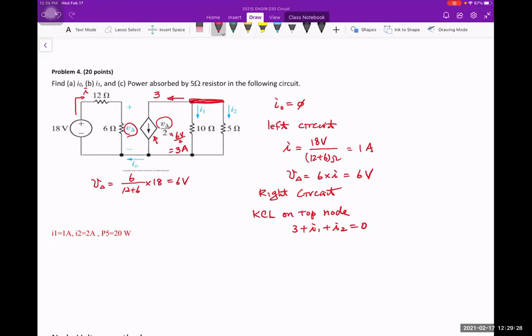Well, actually, if you look at the circuit, you can use the current division because it's a current source in parallel with 2 parallel resistors, right? Also, you know the net current is 3 amp, and the net current is going clockwise, right? The net current is going this direction, which means that for I1 and I2 the values will be negative, because the current direction should go upwards instead of downwards.